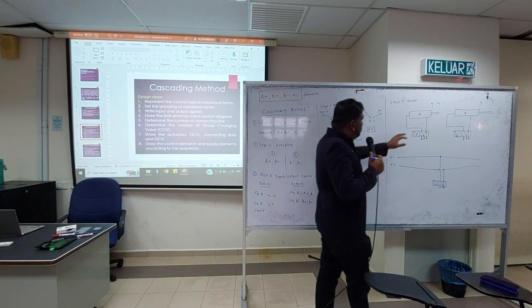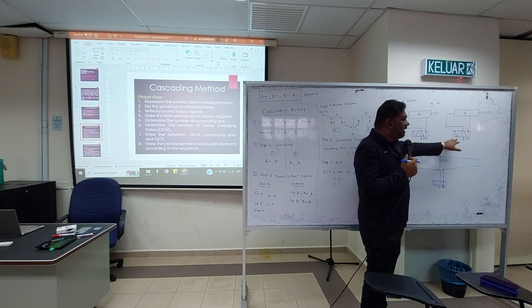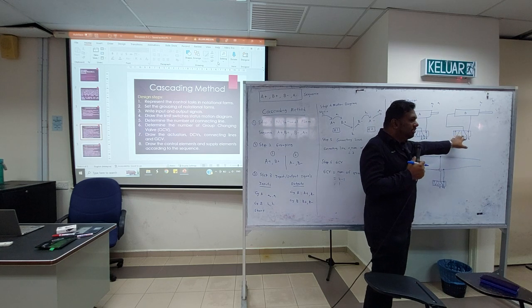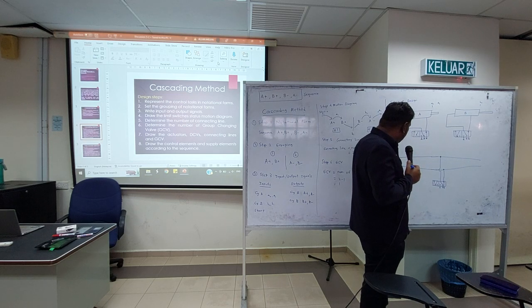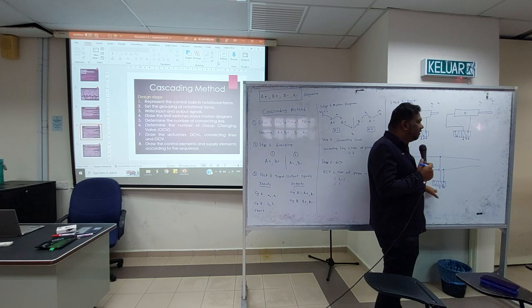So lukis dulu your cylinder. So 2 cylinders, 2 controlling directional control valves. Okay, each cylinder will have 1 directional control valve to control. Okay, 5/2. Then you have 2 connecting lines. So group 1 and group 2. Then you have a directional control valve to switch.